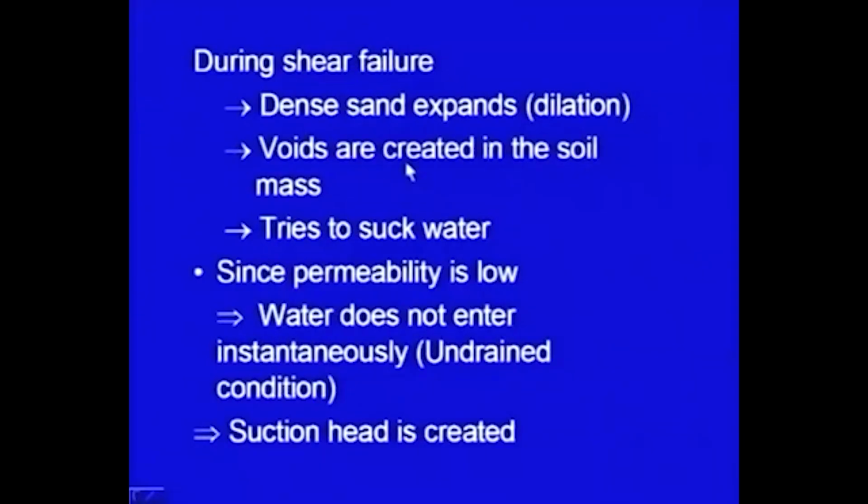Now, again this is filled with water. So, what happens when the void is created in the soil mass? The soil mass tries to suck water, and since permeability is low, water does not enter instantaneously, and the undrained condition will prevail in the soil mass.